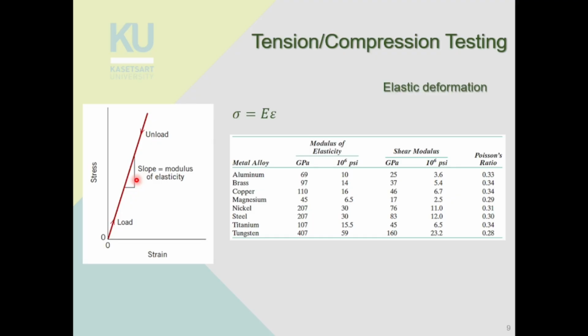Right? But at the same time, you cannot choose a material with too high an elastic modulus, because usually materials with too high an elastic modulus are really brittle. So it will break easily, right? It might not bend much, but it bends just a little bit and then it breaks straight away. So we don't want that either. You have to pick a material with a high enough elastic modulus so that it doesn't bend too much, but the elastic modulus mustn't be so high that it becomes too brittle.